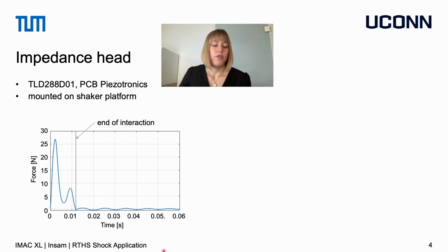This force comes from an oscillation of the shaker, and remember that the shaker moves according to the simulation of the mass spring damper system, so the mass spring damper system vibrates with its eigenfrequency after the interaction period. However, since there are no interaction forces anymore, we expected that the force would be zero. So we asked ourselves why we still measure something and looked into the sensor drawing.